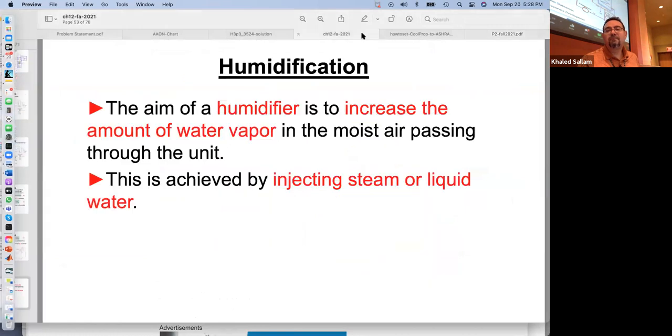So that's what happens in evaporative cooling, when the water has no source of energy but the air that is trying to carry it around. And so the air will drop. But what if the water is really hot, hotter than the air? I mean, of course, the air will not get cooler. It may even get hotter.